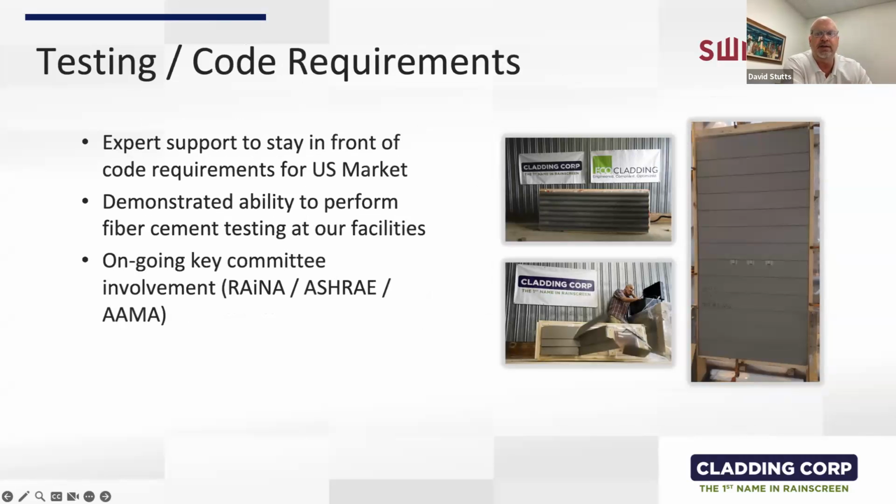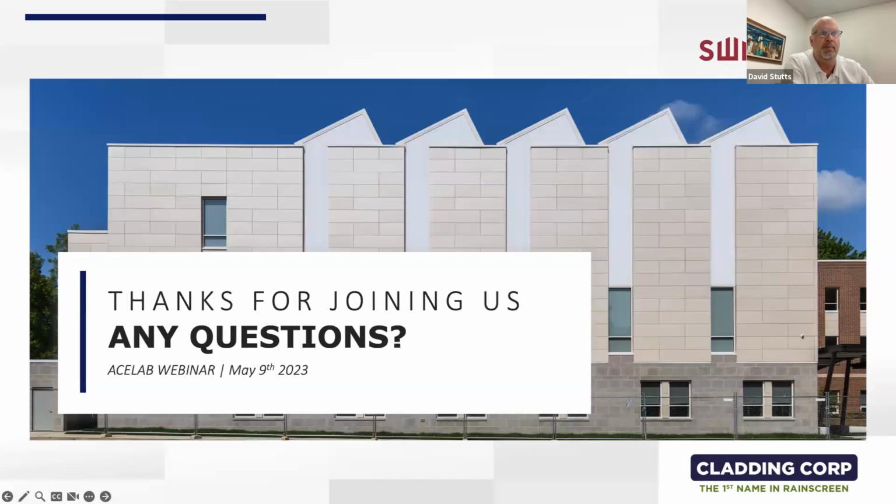What we've tried to do today is give you a background in reference to fiber cement panels. We also work in terracotta and ceramic. I would consider the classic scenario of Rainscreen panels to be ultra high performance or fiber concrete panels. The main difference between fiber cement and fiber concrete is that they'll both be air cured, but you just have more aggregate. Depending on which company you work with, some are extruded, some are poured products, where ours definitely use the Hatschek approach in reference to production.